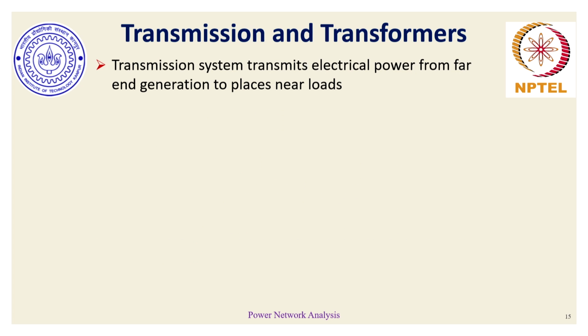Coming to the transmission level, why is transmission essential, necessary at all? If power is being generated at generating stations at around 20 kV, and if we look at the history of Indian networks, typically these voltages were very low, and the issue was that power could not be transmitted to far off ends at low operating voltages, because a lot of power was being used up as I square R loss. So basically the efficiency was very poor.